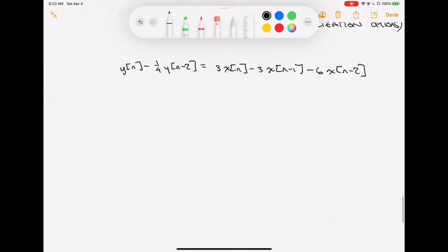I would like to start thinking about getting structures to realize this system. And to do so, I'm going to take a look at this guy's transfer function. So I would like to get the transfer function of this system. That is the h of z. This is going to be easier for us to manipulate and be able to see some different options for realizations that are either series or parallel as well. Transfer function we know is what? This guy should be something like a P of Z by Q of Z. This is something we talked about in a previous lecture.